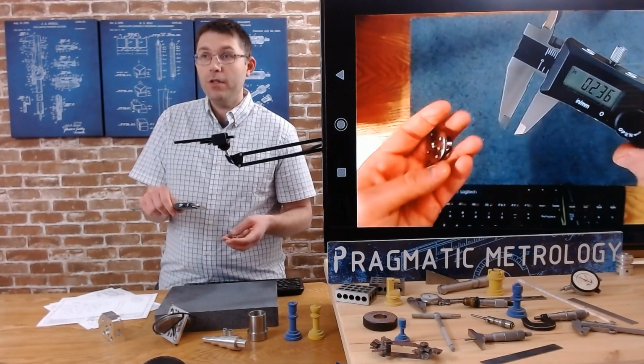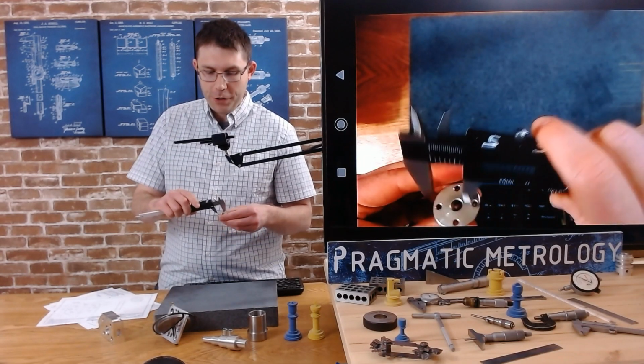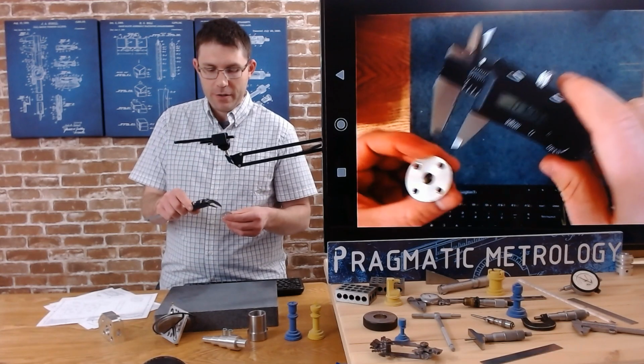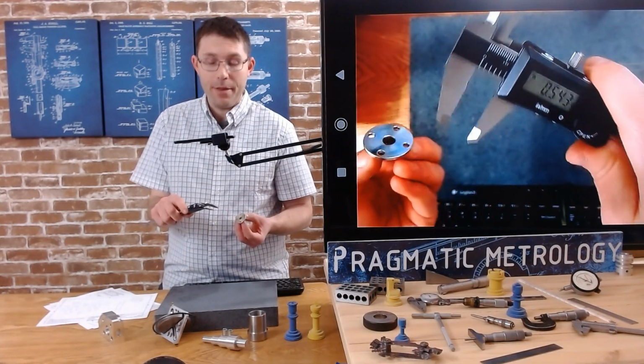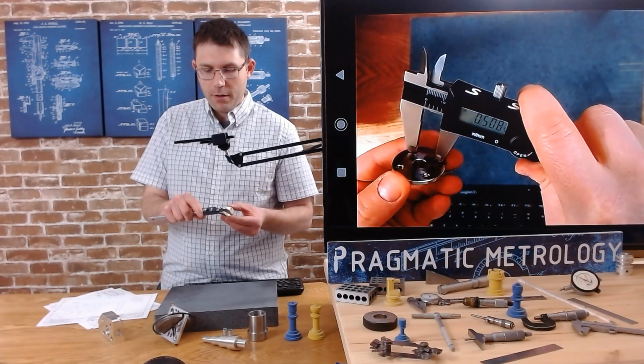Another way you could do this is you could zero the caliper on one of your features and check that way. So I'll do this next check with that method. I'm going to zero it equidistant here, 508.